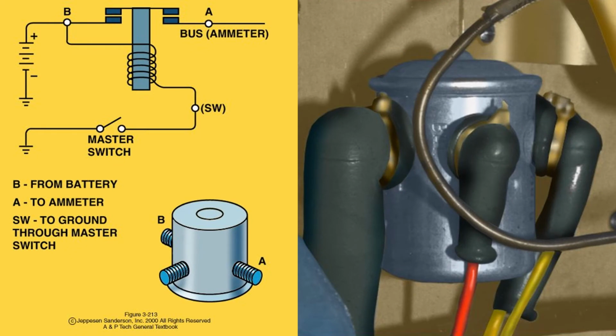Our small single-engine aircraft typically have two relays, a battery relay and a starter relay. They are in series with each other, and the starter relay cannot be energized until after the battery relay is energized. They operate by supplying a small amount of current to a coil, which creates an electromagnet that closes a set of contacts, allowing a larger current to pass through.